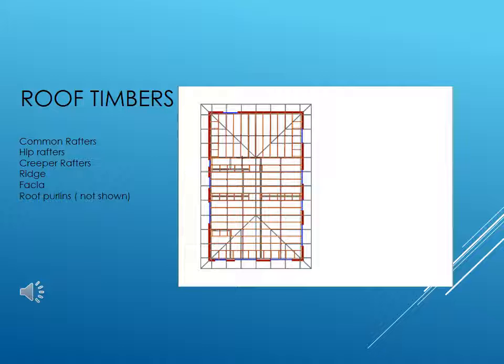So when we see this layout, we can see that I have also not put in bracing, and that would be an additional component. But seeing that we're working out timber sizes, that is more important than the bracing at this stage.